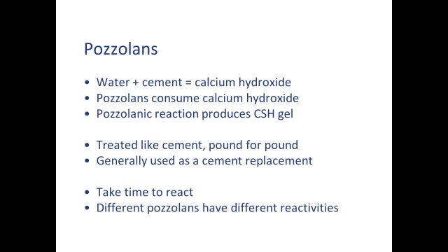When we add pozzolans to our concrete, the pozzolans react with the calcium hydroxide. It's called activation, and it's called alkali activation because it needs a very strong alkaline solution to do it. And that alkalinity reacts with the chemistry of the pozzolan to form more of the calcium silicate hydrate gel, which is the desirable glue that holds everything together. So we're making more glue from the waste product is what we're trying to do.